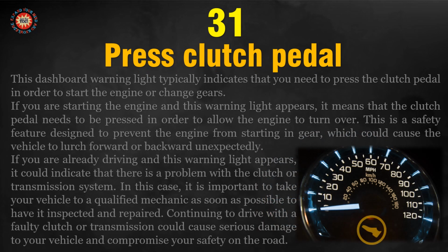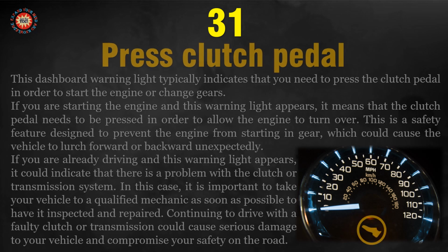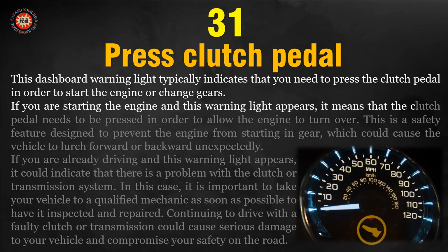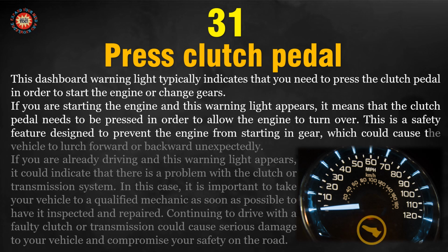Symbol 31. Press clutch pedal. This dashboard warning light typically indicates that you need to press the clutch pedal in order to start the engine or change gears. If you are starting the engine and this warning light appears, it means that the clutch pedal needs to be pressed in order to allow the engine to turn over. This is a safety feature designed to prevent the engine from starting in gear, which could cause the vehicle to lurch forward or backward unexpectedly.